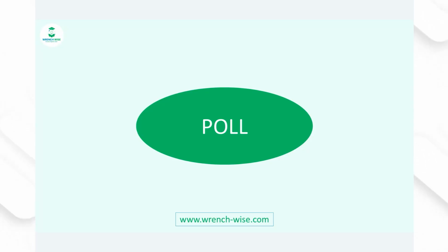Let's do one more. Okay. So if you decide the P1 model is not accurate enough for your fire simulation, what happens if you use the FVDOM model with standard S4 quadrature? What are you doing there? So you added one extra equation, you added 24 additional transport equations, you changed the fluid density model only, or you reduced mesh requirement, making the simulation faster. Okay.